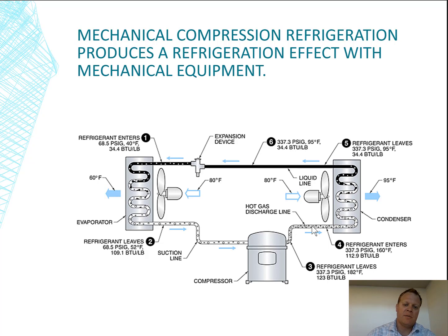The reality is this graphic is a little bit off. The graphic should really start with gas up at the top and have liquid coming out the bottom, because that's how the condensing coil is. But this is a schematic in nature, so it doesn't matter. If it was drawn more accurately, it would show the gas coming in the top, condensing and turning liquid, and going back over here.